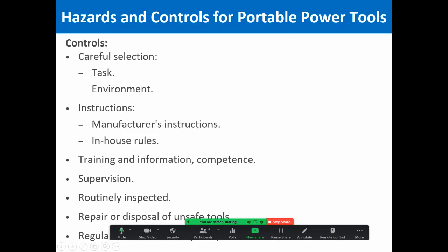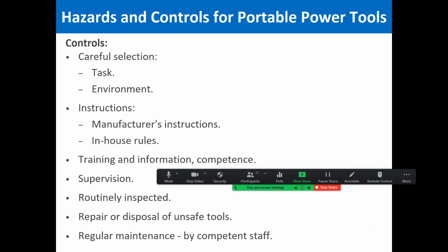You need to make sure that you follow the manufacturer's instruction and follow the in-house rules. Proper training, information, and competence is required for operating the power tools. Adequate supervision should be available. The tools should be routinely inspected to make sure they're in good condition. Any damaged or defective tools should be repaired or disposed of, and regular maintenance should be carried out by competent staff.